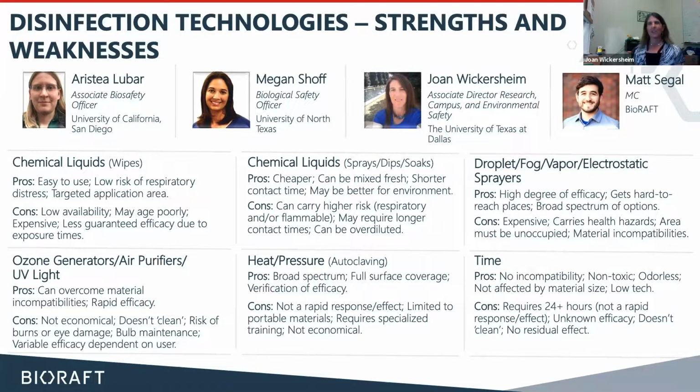When you're thinking of filtration, remember that it's not just about the pore size of the filter. Filters have a lot of different mechanisms of action. There's deflection, there's electrostatic attraction, there's all kinds of things that go into the nature of filtration. So it's not just how big or small a virus is and whether or not it could fit through a pore.